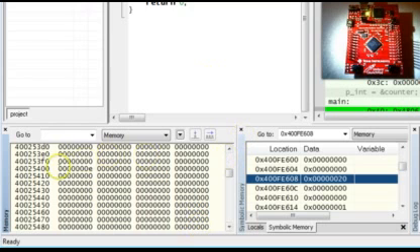Scroll up to this register and first just set bit 1 by writing hex 2 to the lowest nibble, again remembering that the bits are always counted from 0. Hey, it worked! The red LED lights up. You should give yourself a big pat on the back. Try to turn the LED off by writing 0.